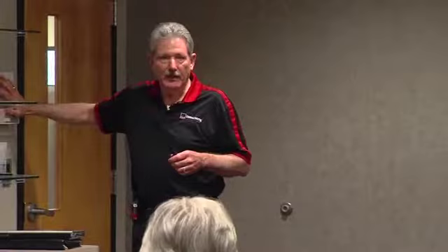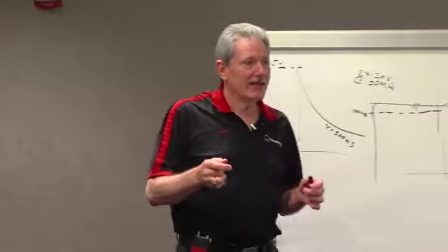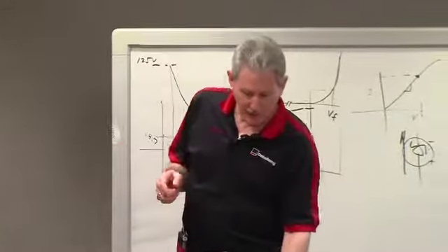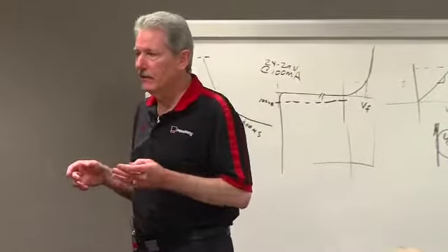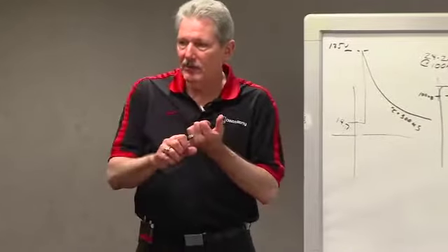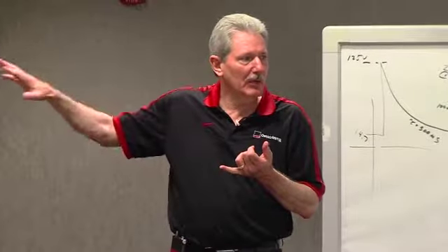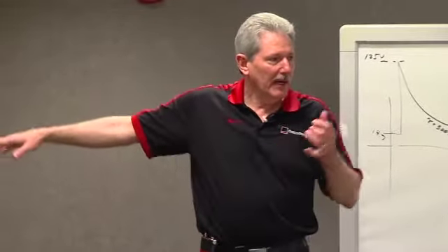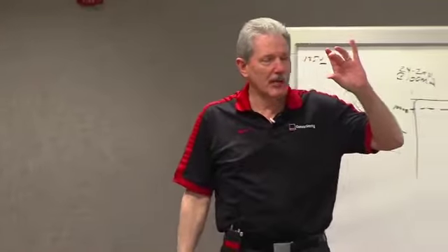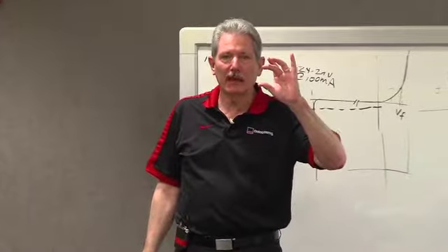This is a regulator. It's a thermostat. This is set at, I can't read it, 72 degrees. That is the set point. If you look at the critical parameters on a voltage regulator, obviously we have to have the right set point, and that right set point is so that we can properly charge the battery. The battery only charges optimally in a very narrow band.